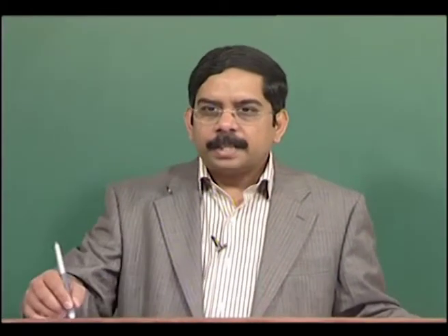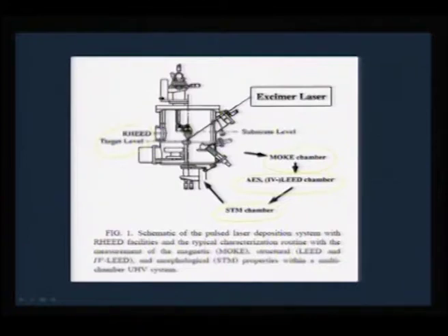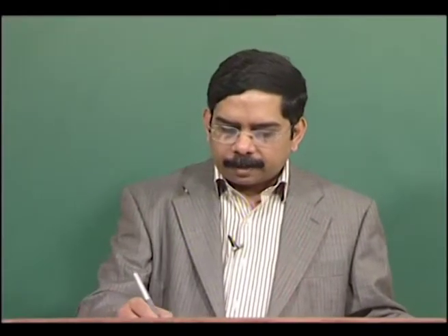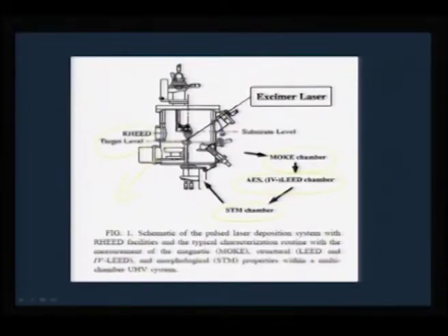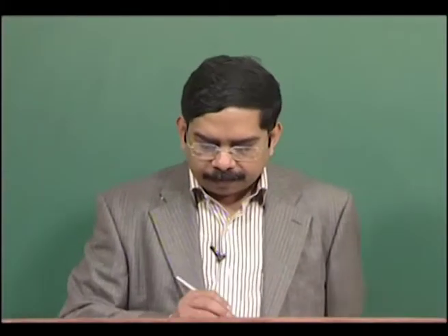So that way it is more friendly, you can play around with a variety of materials. But in MBE you never get to break the vacuum, so it is always inside the vacuum chamber. Therefore you need to circulate your sample from the processing chamber to the characterization chambers. Again you clean the crystal, again you go into this. So it is a loop. But in PLD, after this you can come out and do measurements in an AFM or an STM chamber. You can do a measurement on a LEED chamber. So this gives a flexibility to play around with different systems.